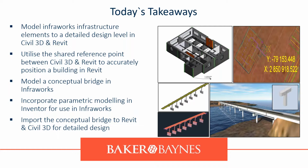And we then exported that to Infraworks, added it to our library, updated the bridge to match it. And then, of course, we exported an IMX file, we published a civil structure, and we imported that into Revit and Civil 3D, where we could do the rebar in Revit and also the sheets, as well as in Civil 3D for placement along the plan and profile drawings and long sections.